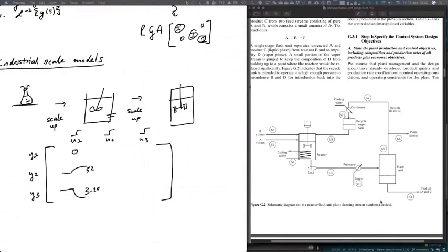And so you can't simply say, well, this is the way that you do this. You have to start with the objectives. And if your objective is to maximize valuable product, that leads to certain decisions, right? And quite a lot of these two appendices, F and G, they are really the core of understanding control philosophy, because it tells you that you have control objectives, and most of the time, like every objective that you have in life, you will find that your objectives are contradictory or not all simultaneously attainable, right?